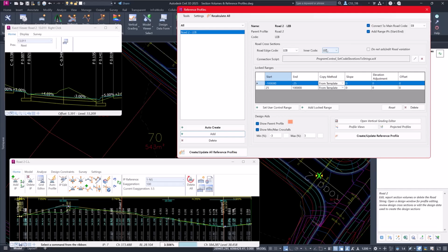Because if you imagine you're manipulating back of curb, and you set the relationship from centerline to back of curb and you forget to fix up that it's got to keep the curb shape together, you're going to get warping happening between the back of curb and the top of curb rather than the center line and the edge of bitumen. So very much like the inside code on our horizontal variation for manipulating the crossfall. And then underneath, it's set up the locked ranges.